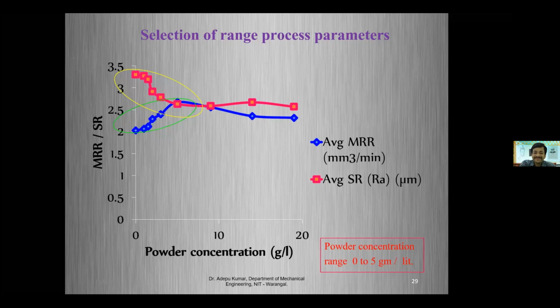No, it is useful, because what I am saying is, if you use an L array, from the L array you generate the equation. That equation you can optimize by applying any optimization technique, so that you can get beautiful results. If you are not using the Taguchi method, once you get the equation, you need to conduct a larger number of experiments.